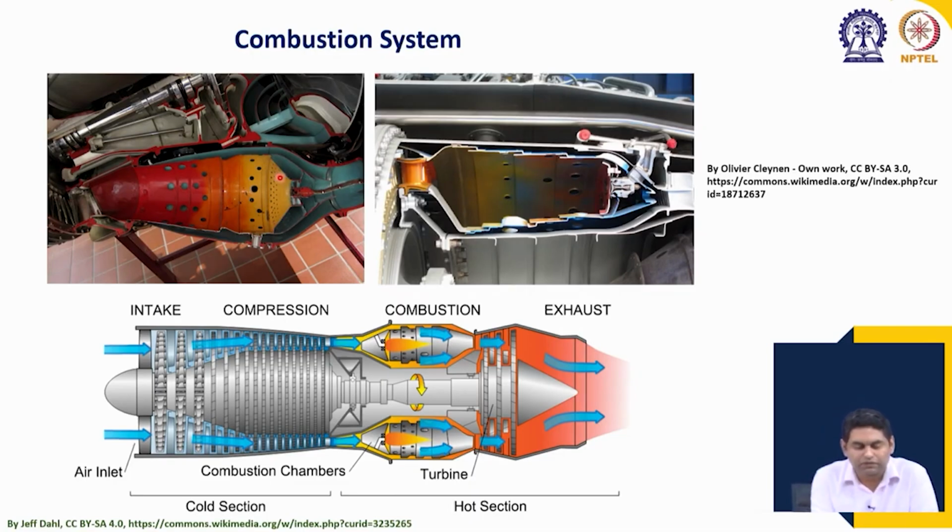So, the role of this combustion chamber is to assist with this combustion process, have continuous combustion with less emission and have very uniform temperature variation at the inlet of the turbine. So, very uniform delivery of the combustion products, and the combustion should be fully completed within the short time which the gases have in this combustion chamber. This time is of the order of much less than a second. So, we need the combustion to be completed before that. Okay. We will go into further details later on.